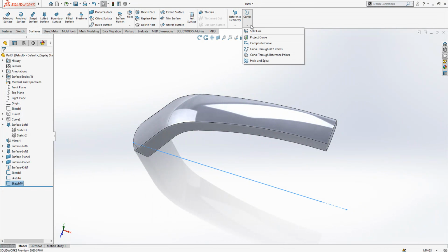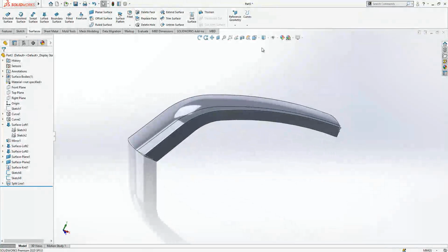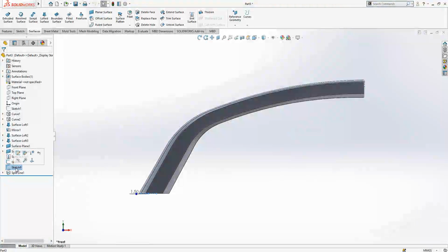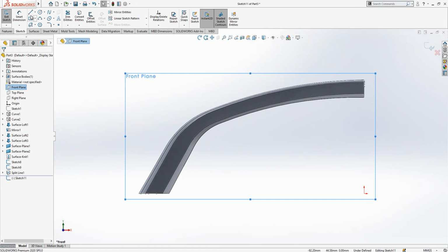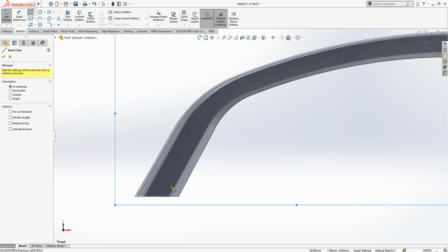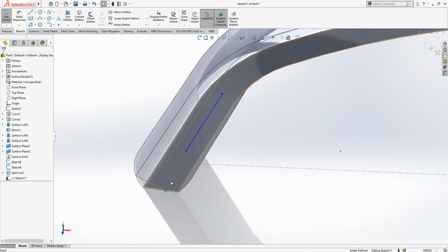So we constrain everything. We don't leave to chance the capabilities of the loft. We control every point. That's the point of all this example. You will not find this kind of example a lot. People just make profile to profile loft and done. But in real work, it is very different. You need to control everything, the curvature, the position of all the connections.